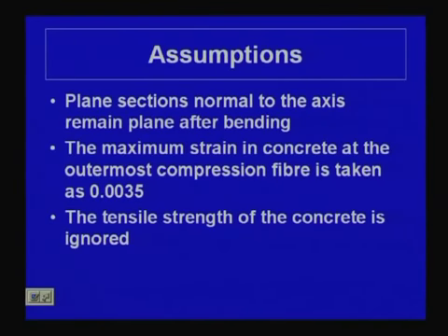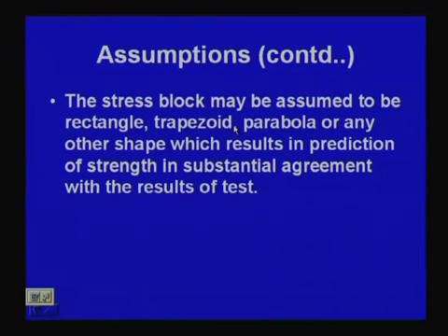The stress block may be assumed to be rectangle. I shall come within a minute to what a stress block is. The stress block may be assumed to be rectangle, trapezoid, parabola, or any other shape which results in prediction of strength in substantial agreement with the results of test.